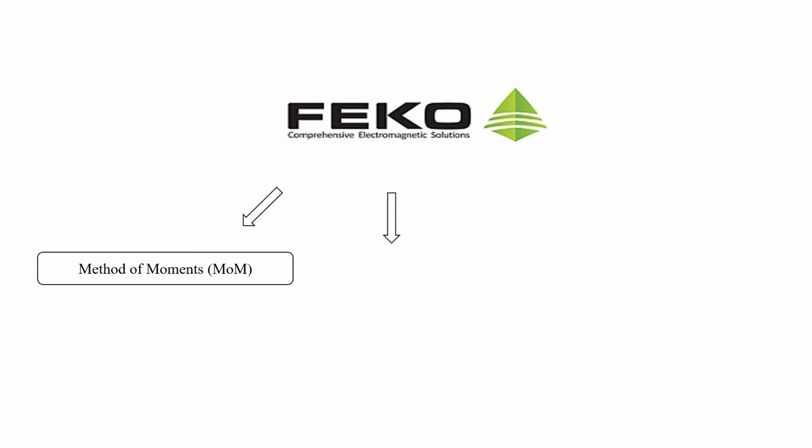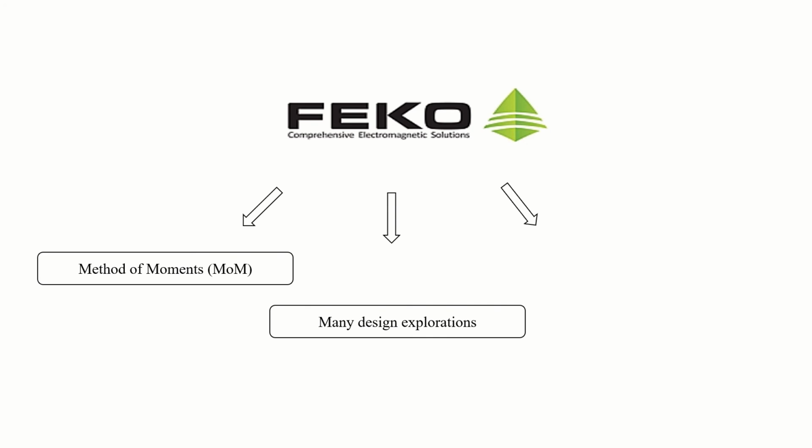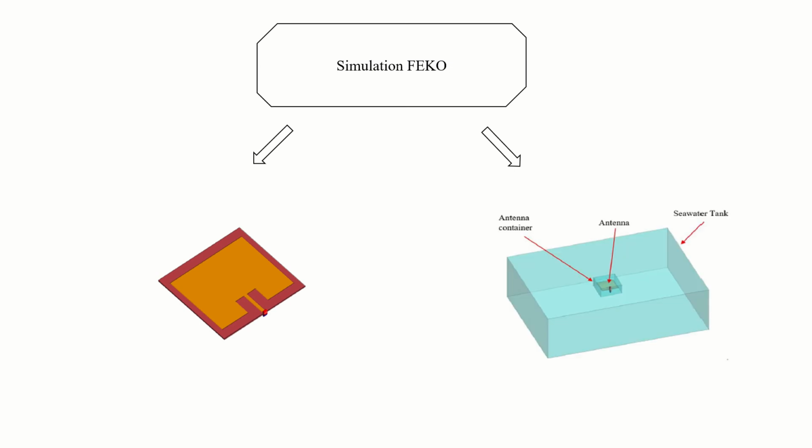Optimization during early prototyping is also used to explore design possibilities where the internal geometry and ground plane are considered. The MoM solver produced very successful simulations in each step, allowing for much exploration of design. During the simulation, the mesh antenna will be simulated in the free space environment, then it will be tested in a seawater environment where the mesh antenna is designed to be enclosed in a clear case. The result from the free space will be compared with the one enclosed in the seawater environment.